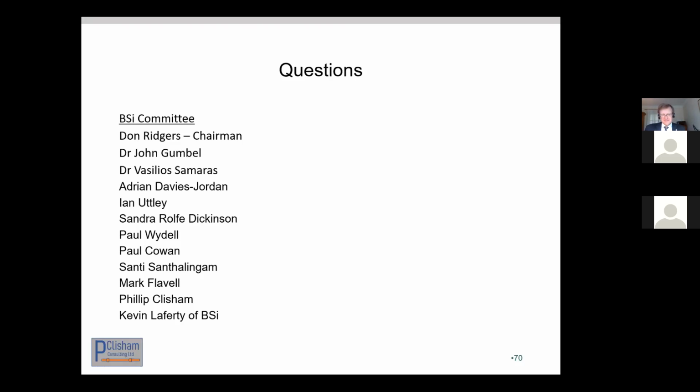The first one comes from, and I apologize, it's Ansha P. This question concerns 160 mil OD P100 SDR11 pipe, which is a pressure main. And the question is, it's to be laid on ground covered with an earthen berm, and it's got natural earth covering the pipe with about 100 millimeters of cover. And the question is, do you think this would be enough to take a pedestrian load?